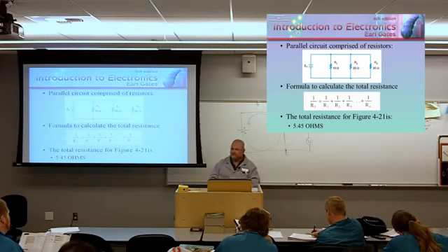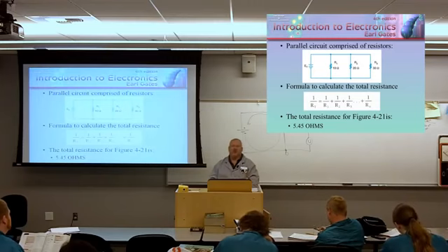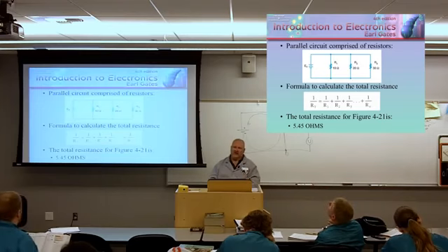So you can guarantee the total resistance will be less than 10 ohms? Absolutely. And if you come up with something other than that, you've screwed up. Plain and simple. So the total resistance of a parallel network will always be less than the value of least resistance. And your assumption is correct. In this circuit, it's got to be less than 10 ohms.